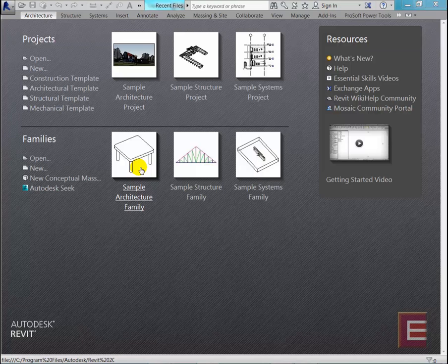This portion of the project is going to transition from Civil 3D to Revit or Revit Structure, where we can perform some structural engineering tasks such as reinforcing or production of structural documentation. A few of the steps that we're going to do here, we're going to transfer that initial bridge from Civil 3D into Revit. We're going to then make some changes to that bridge definition within Revit, and then we're going to move that bridge from Revit back into Civil 3D.